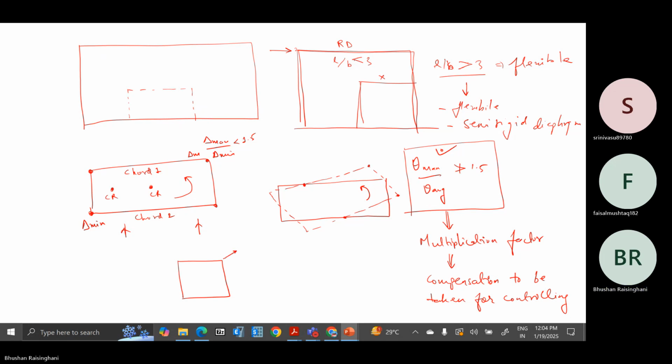In the book of the guideline by Dr. CVR Murthy, this is already mentioned. If you have gone through that, you would have understood. Due to the application of the lateral force, this building is moving in diagonal direction. This is a feature mostly in square type buildings.